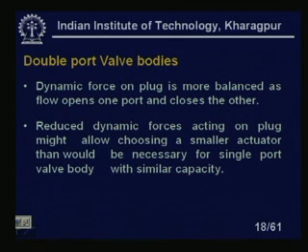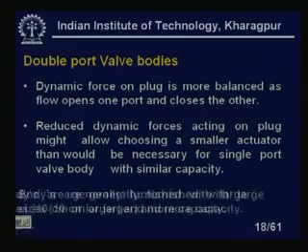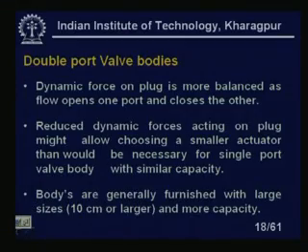Reduced dynamic forces acting on the plug might allow choosing a smaller actuator than would be necessary for a single port valve body with similar capacity. So I need a less powerful actuator, and that is the reason the double port valve is preferred. Bodies are generally furnished in large sizes, 10 centimeters or larger, and the capacity is also more for this type of valve.